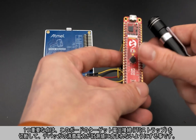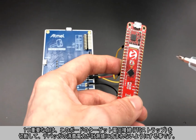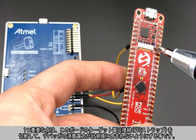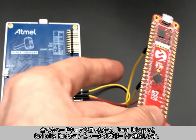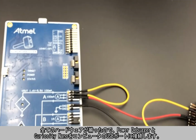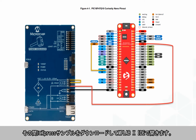One important thing to note here is that the target voltage connection, or VTG strap, on the board needs to be cut as well to ensure that we aren't including the power consumption of the debugger in our measurements. Okay, so now that we have all the hardware set up, go ahead and connect both the power debugger and the Curiosity Nano to your computer's USB port. While you're at it, download the example and open it up in your MPLAB-X IDE like I have here.